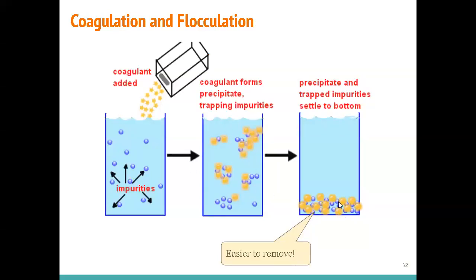So it's not like air pollution, right? Air pollution, we wait and wait for the pollutants to go away. But here in the water, they won't go away, right? So we want them to stick together, and then we remove that. So on the left-hand side, this one is very hard to remove the impurities. But on the right-hand side, because they stick together, we can just scrape it off, okay, from the bottom of this treatment process. It's called coagulation.